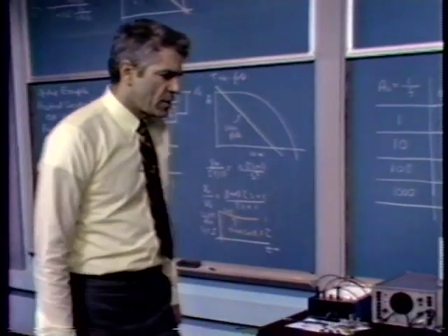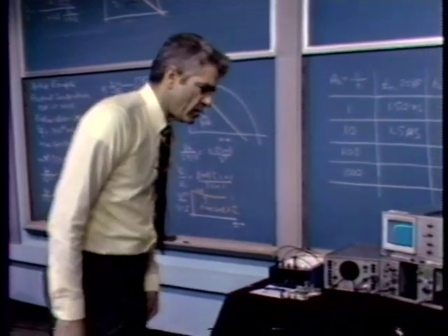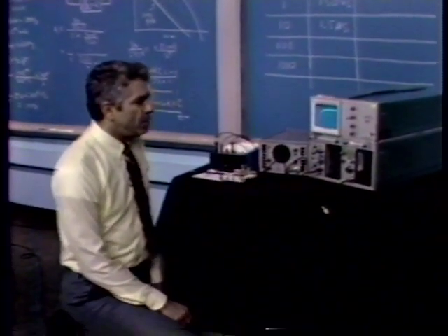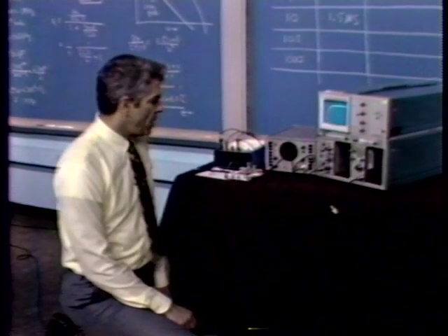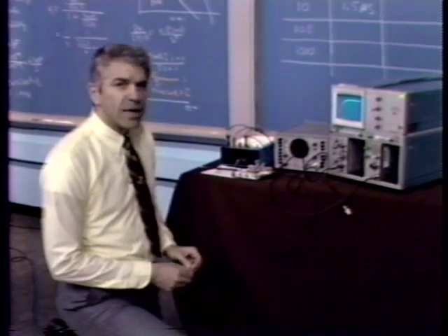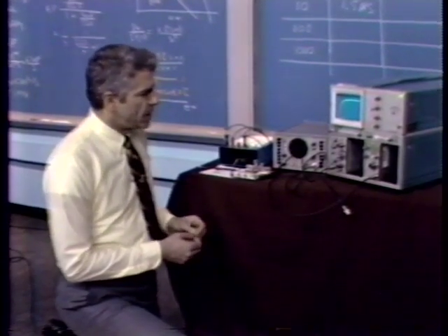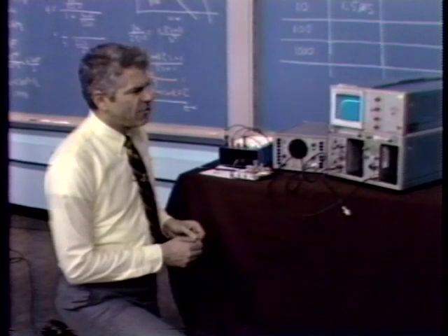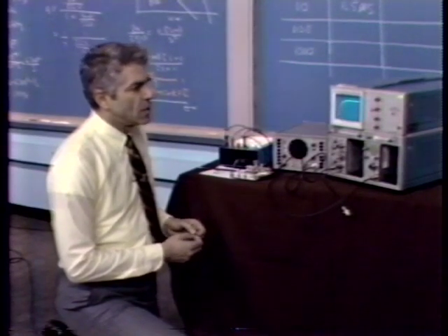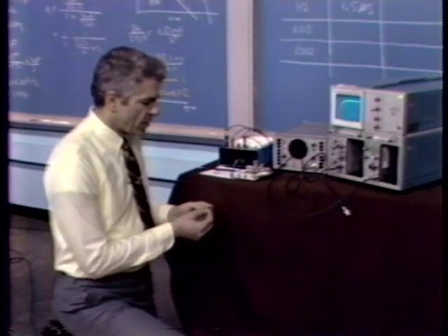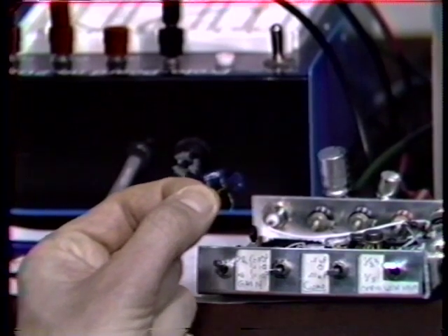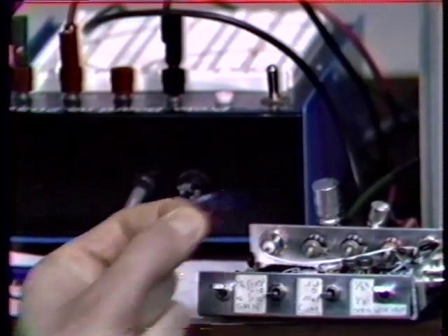However, we have lost the factor of 10 in response time or in bandwidth, and we can buy that back by lowering the size of the capacitor by about a factor of 10. There's a little bit of departure from the ideal case here. There are a couple of effects in the amplifier that actually force us to use a capacitor that's somewhat larger than 1/10 of the previous value. But we've made up a capacitor in that range, of about 3 picofarads or thereabouts.